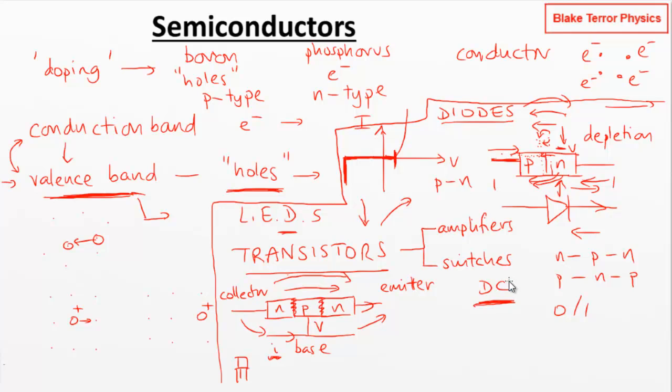And these three connectors are what you see on circuit diagrams, where you get things that look like this. This would be your symbol for your transistor. This would be an NPN one. This is the base that we've got here. Then we've got collector and emitter going on here. The direction of the arrow is telling us about the flow from collector to emitter, and it depends upon which type of transistor we've got. So if you've got the arrow pointing that way, it's NPN. If it was pointing the other way, then we'd have a PNP junction there.